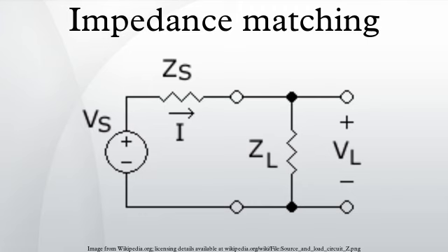If the transmission line is not matched at both ends, reflections from the load will be re-reflected at the source and re-reflected at the load end ad infinitum, losing energy on each transit of the transmission line. This can cause a resonance condition and strongly frequency-dependent behavior. In a narrow band system this can be desirable for matching, but is generally undesirable in a wide band system.